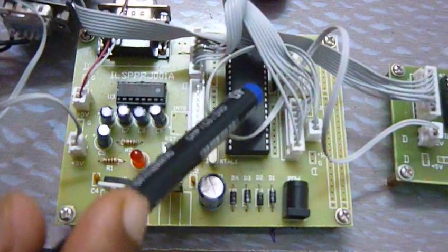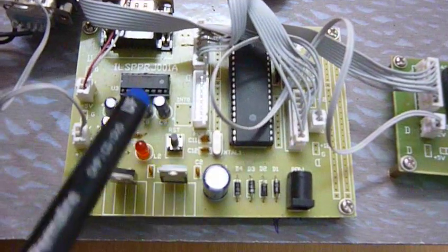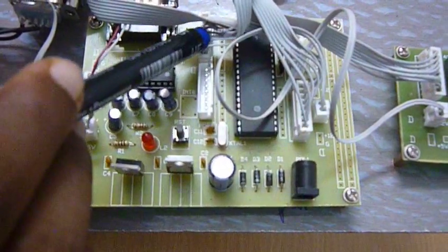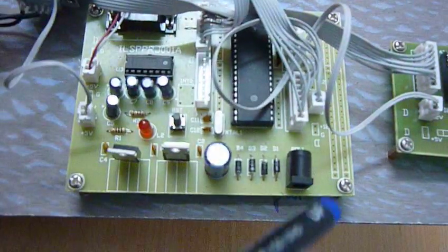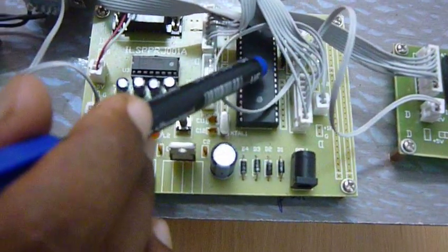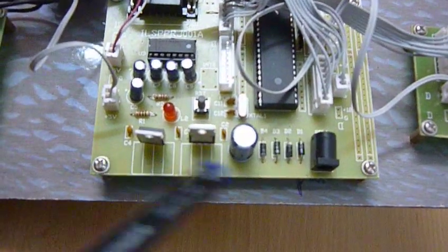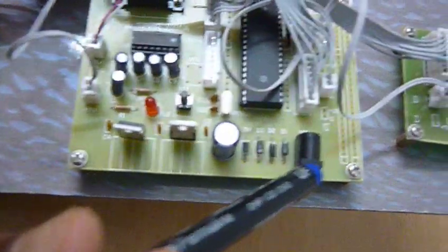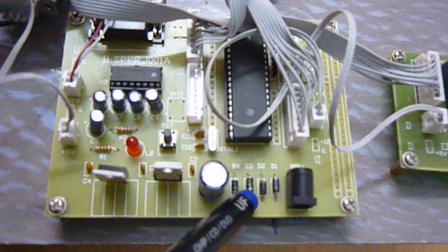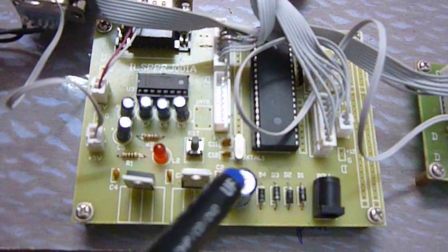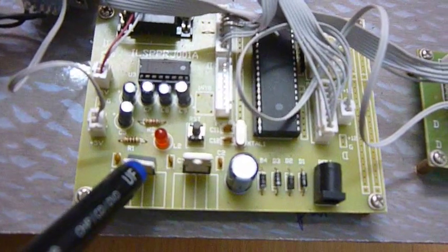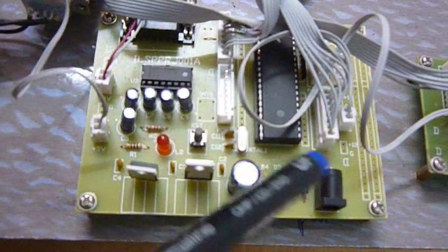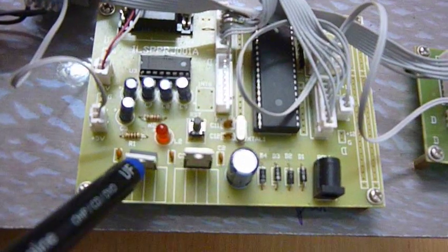Coming back to the main board, we have a microcontroller here. This is a 40-pin microcontroller. This consists of 4 parallel ports, port 1, port 3, port 2 and port 0 respectively. For powering this microcontroller, we need a power unit, which consists of a power adapter followed by a bridge rectifier, followed by a filter capacitor, followed by a voltage regulator. This is a 12 volt regulator and this is a 5 volt regulator. And this 5 volt regulator and 12 volt regulator supplies 5 volt and 12 volt respectively.